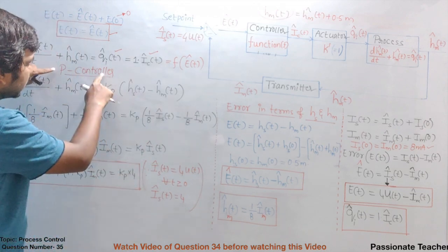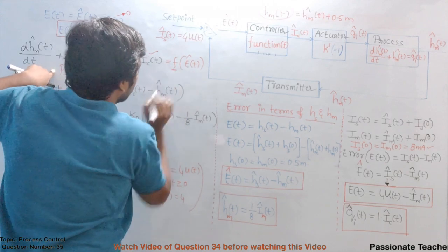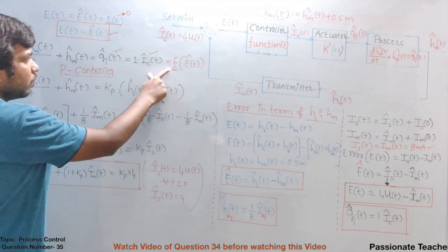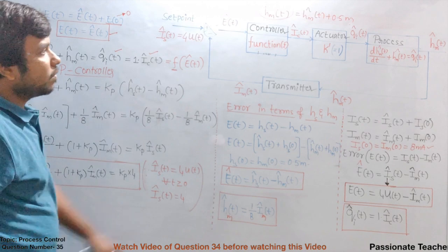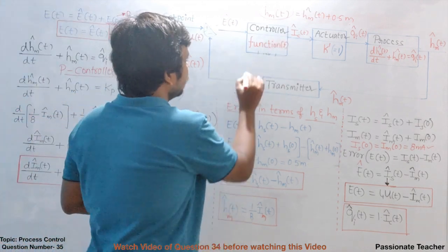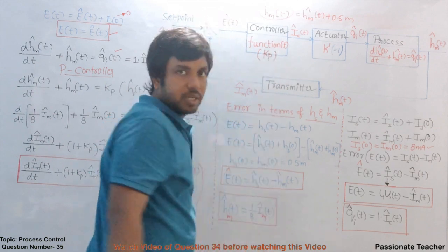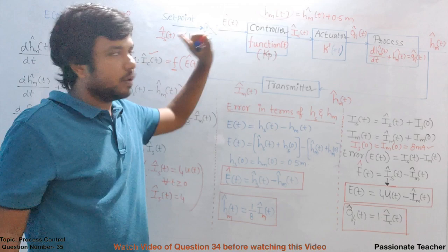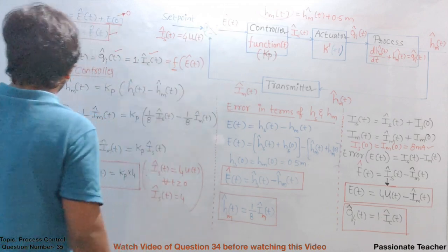It means that for a proportional controller, whatever the function we have used here, mathematically, is nothing but a simple constant. So we have to write this f as nothing but Kp, nothing else. That means this value now is going to be a simple Kp, that is a constant gain. So Ic cap of t is equal to Kp into E cap of t. This is what I would like to say. Now if you use it like this, how will the things change?